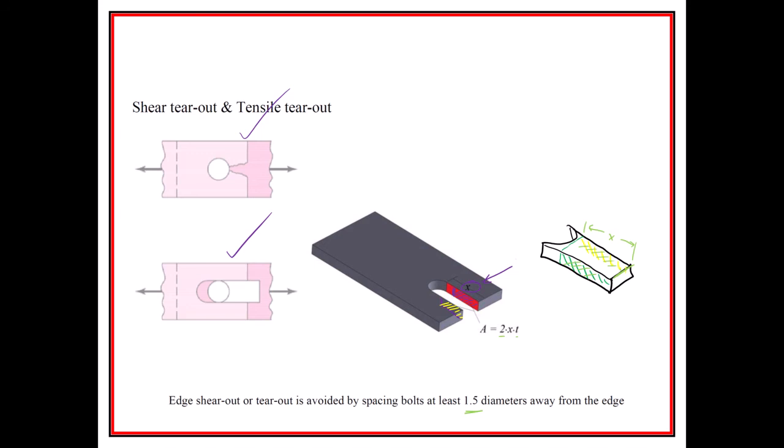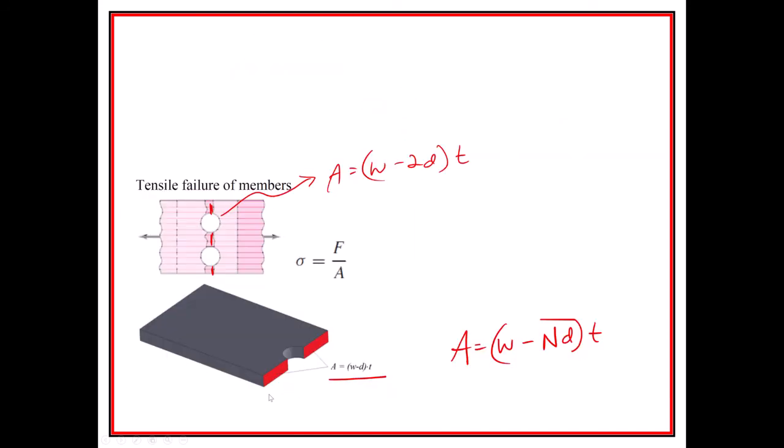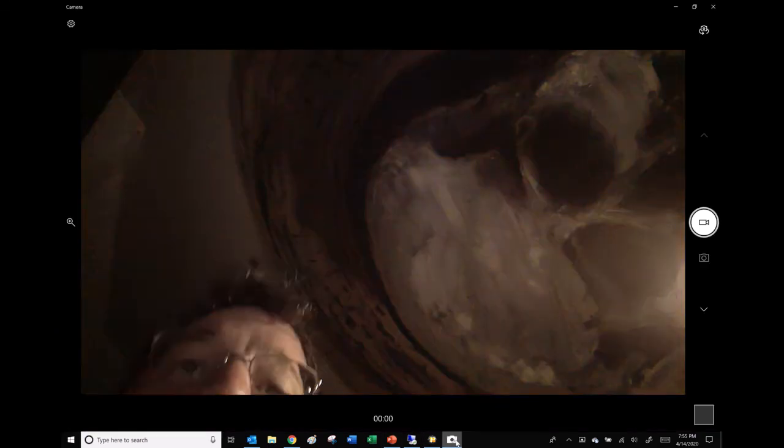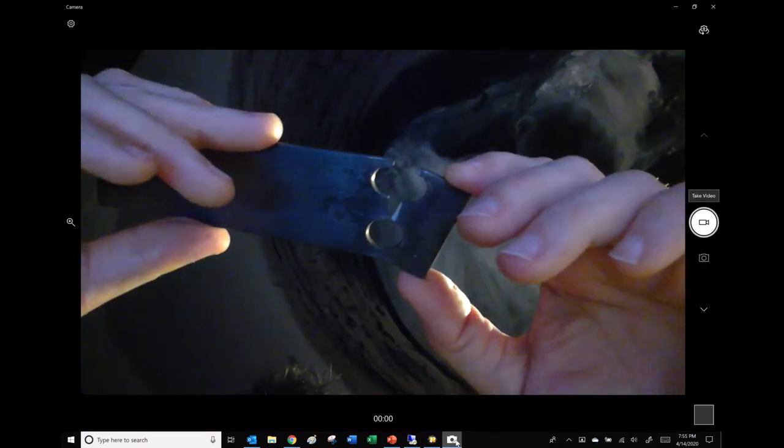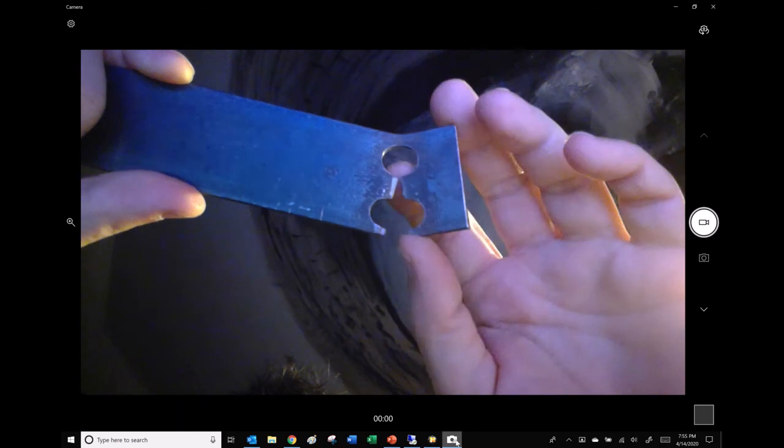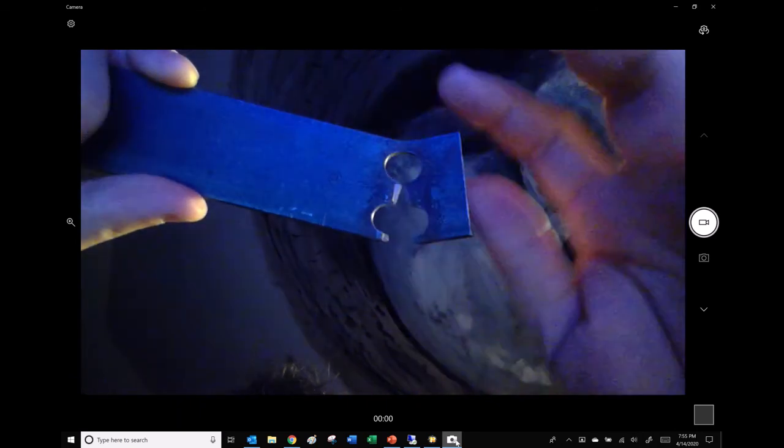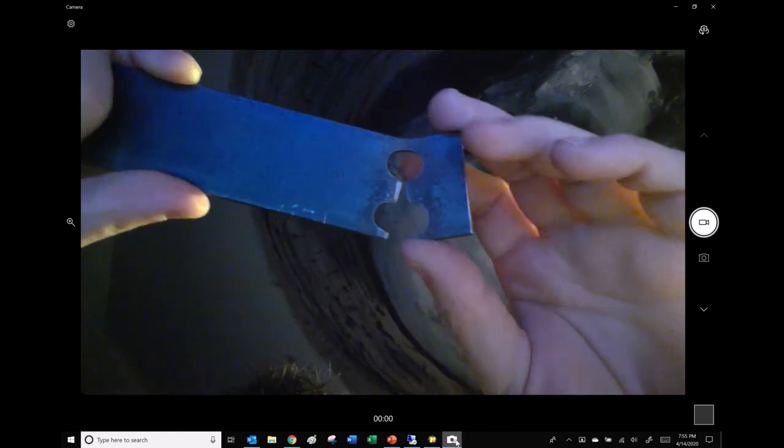And so let's see a couple of different failure modes that I didn't bother to show right here. I think this guy right here, I have really 2 examples of him. I'll discard it, why not? So right in here, you can see that's definitely a tensile failure. There's a lot of material missing because of these holes. The holes are pretty big, so it makes what's left of it weak. Right, so it was weak right here, and it was definitely weak right there. So that's the part that left.